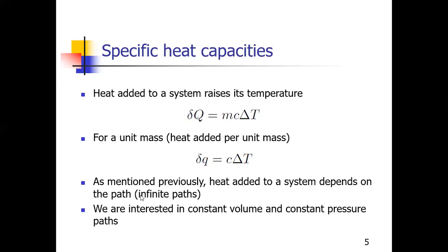If it is a constant pressure path, at what pressure you are adding, or if pressure and volume are changing, something like that, right? So your del Q, it is del Q, it's not dq. Why? Because how your pressure and volume change is going to change how much heat was added. So del Q is a path function also.